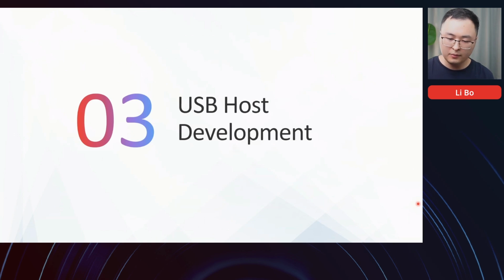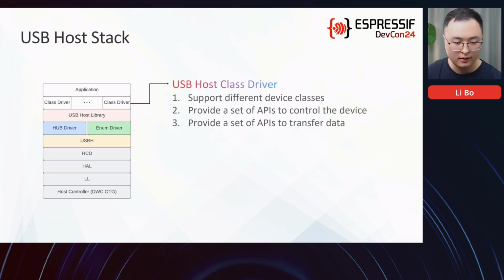Okay, let's move on to the development part. First, let's talk about the USB host stack and the host classes. This is the USB host driver stack in ESP-IDF, which is divided into several layers from the bottom LL layer to the top class driver layer. For most users, you only need to focus on the class driver layer, because it provides a set of APIs to control your device and transfer data.